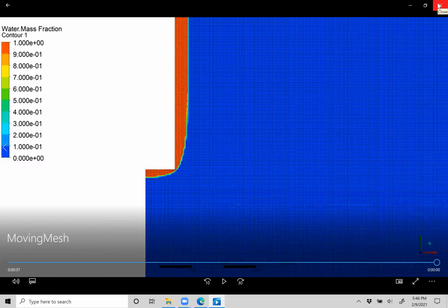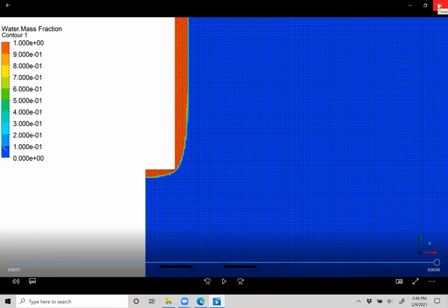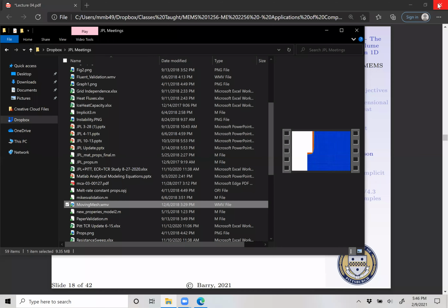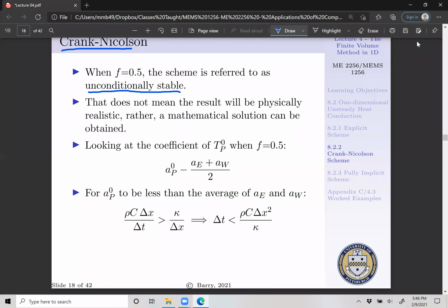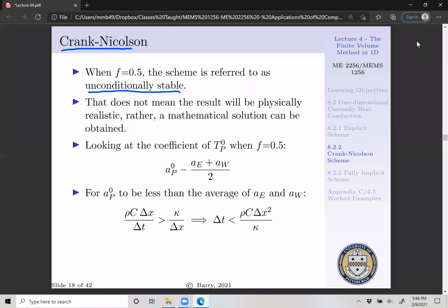In doing this, though, they had some of the most amazing colorful pictures of where the temperatures were above the Planck temperature. Things were going crazy. And that was really related to the time step. They said, okay, well, we have an implicit solver. Let's crank up the CFL. Yeah, just because it's solving doesn't mean you're going to get realistic results.